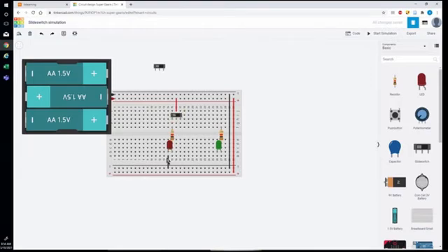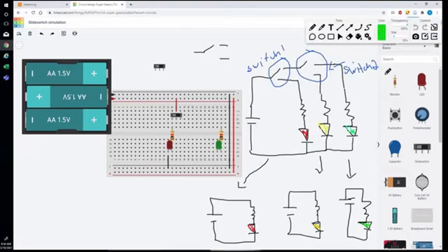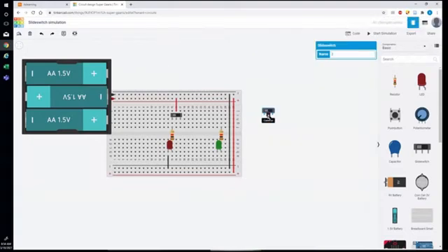So the first terminal was connected to my red, and the second terminal, if you look at it, was connected to the common of the next switch. Let's look at this switch. This is my common, and I'm going to go ahead and run a little wire from the second terminal to my common. So right now I have power running into the common, into terminal 1 when it's selected.